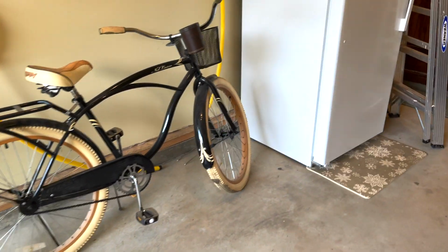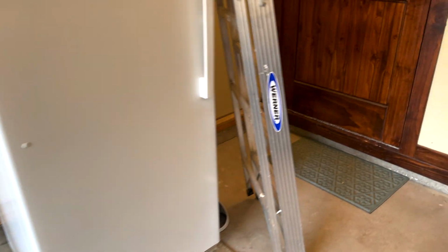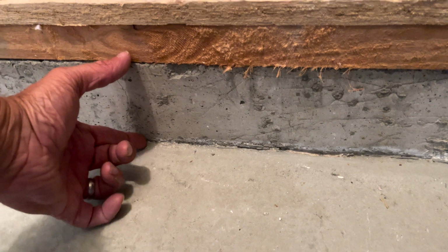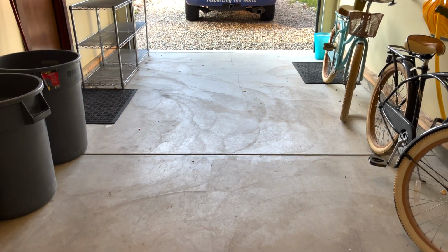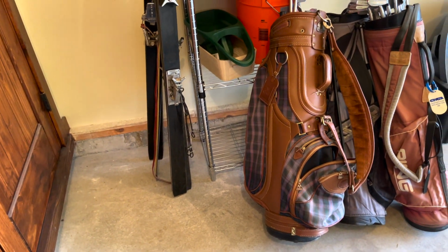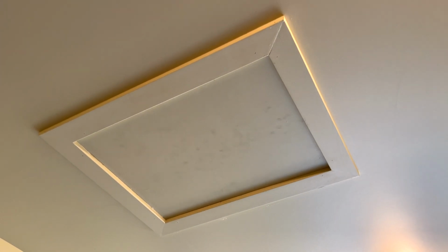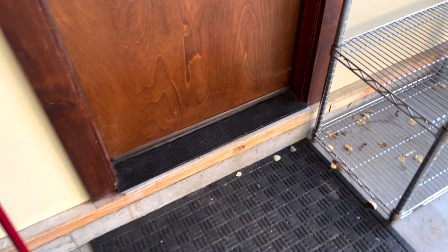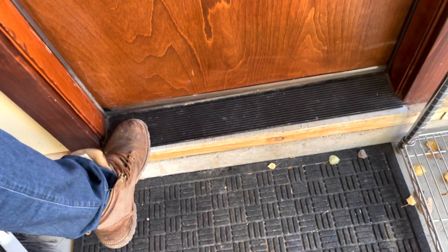Now, over here, I see that the foundation is exposed, and it's about that tall, and it's about that tall all the way around. It's not sloped. This floor doesn't seem like it's sloped, so water goes out the door. And we have a firewall breach. Can't have an opening in the garage. That can't be there. And then we have a high step at the garage door.